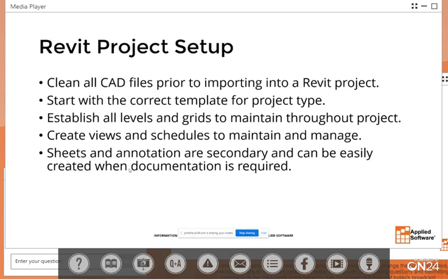But the CAD files need to be clean. One of the things that when I teach AutoCAD is to always use the audit, purge, clean up your CAD files, flatten them out, make sure that things are not non-coplanar, all over the place. CAD files can get real messy. You can have a real big CAD file with 30 XREFs, and only 2 of them are being used, and all the others are in a state of unloaded or unreferenced, right? So bad CAD practices brought into Revit is not good. That's exactly what you want to avoid.